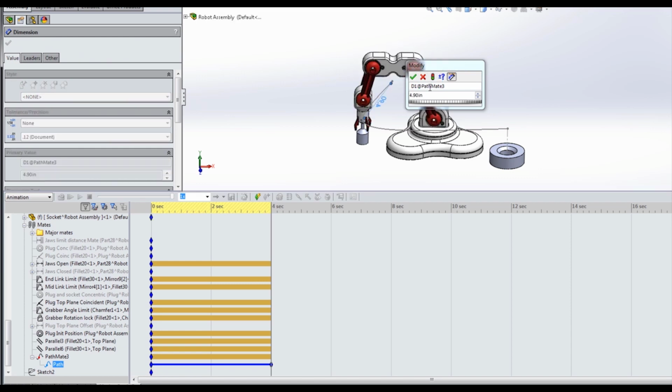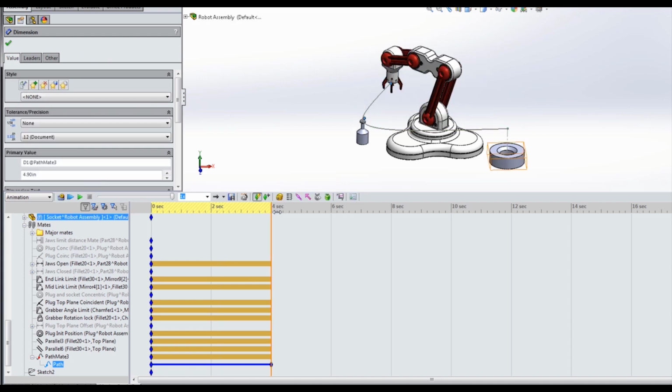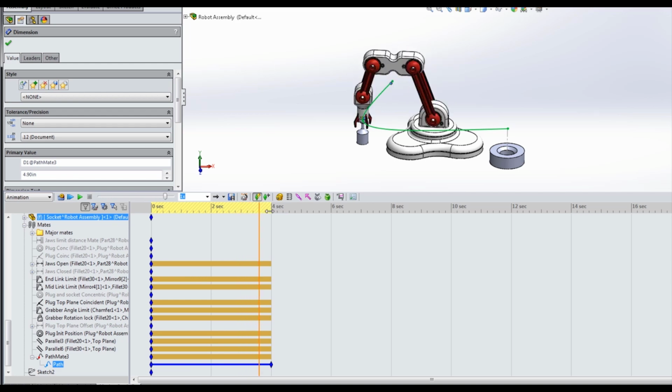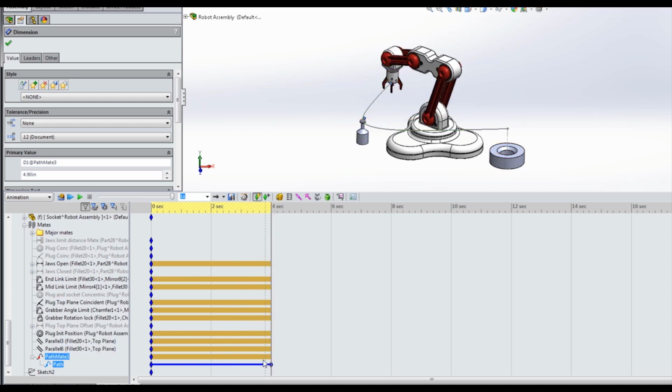We're just going to rebuild that and manually drag this around to take a look at the motion. So as I said, for whatever reason when we play it, it's not showing it properly, but as we manually drag this around, we can see that the motion is right. Now one thing that you do want to do whenever you're creating this motion, you want to right click on the second point and take a look at the interpolation mode.